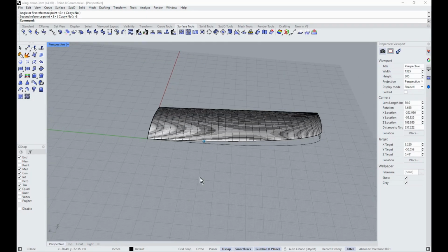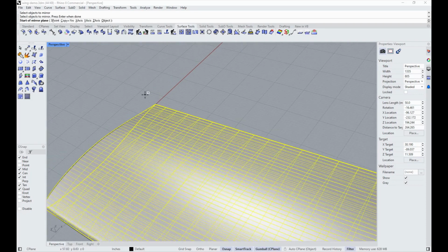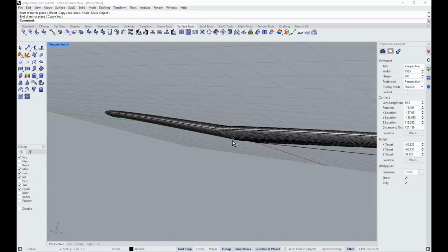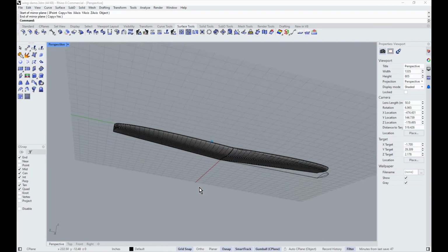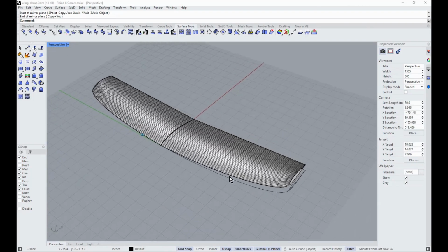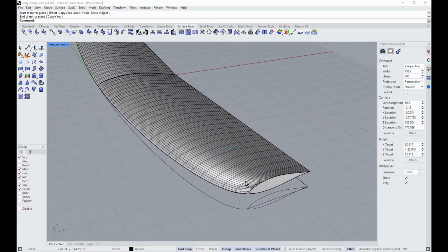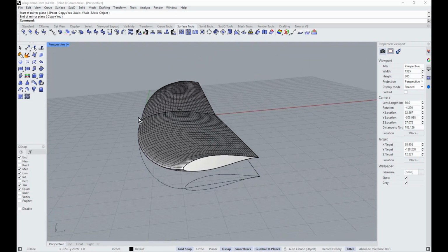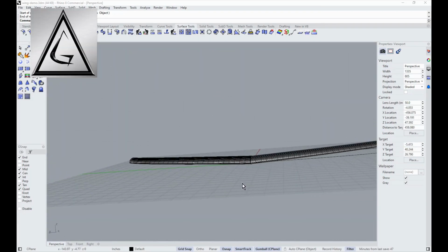And then you can do a mirror. And we'll go in and try to go grid. Make sure the grid is on. And you'd have to patch up the middle here somehow, like cut it and bring it back together. But there you go. That's your light sport Scimitar wing with a 65-415 at the root and a 63-618 at the tip. 3 degrees of tip washout, 55-inch root chord and 30-inch tip chord. So that's just showing the whole thing and the power of Rhino.